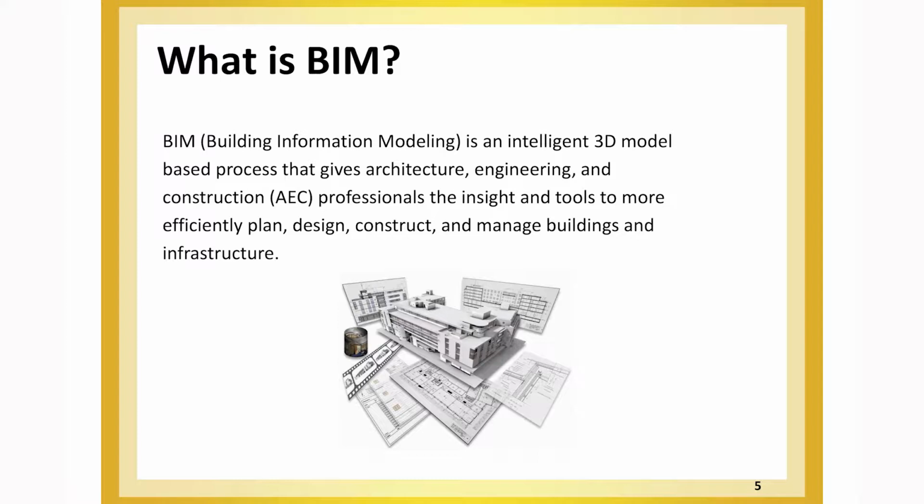And everybody knows where their no-fly is? It should. Yeah, that's another thing, like you do a BIM execution plan, you discuss things like that above the ceiling. You start with your sloped pipe and things like that that aren't going to alter, and then you determine your zones. You try to stick to that a little bit, but it's always a challenge. And you can reference in everybody else's models and see where they are. Right, to make sure you don't have pipe and cable tray.